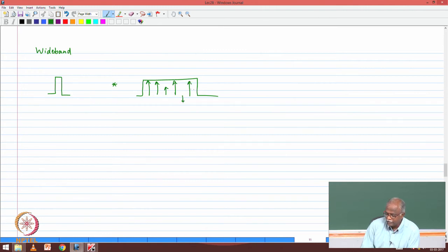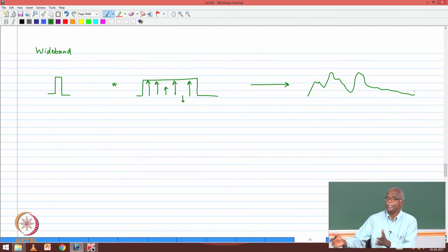Okay, that is the impulse response of the channel. So, the pulse is much narrower than this. So the convolution of these two produces a totally distorted pulse, and it's much longer in duration than what I transmitted. This is why an equalizer is needed: intersymbol interference.